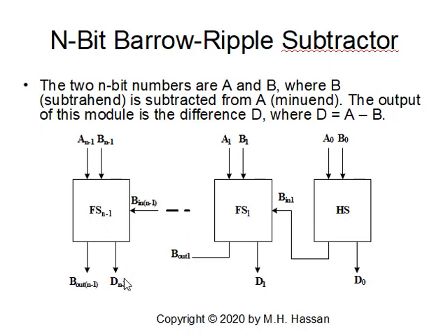So by this, you will perform the n-bit borrow-ripple subtractor, and it also has a lot of delay because of the ripple effect of the borrow that we have to feed into the successive stages until the last stage, and you have to wait for the last answer after the propagation delay has been executed and the answer is fully registered at the output. So this is an n-bit borrow-ripple subtractor.